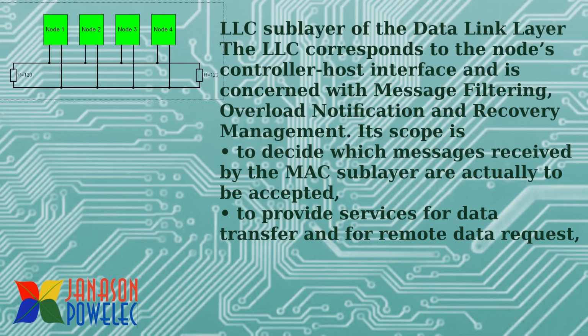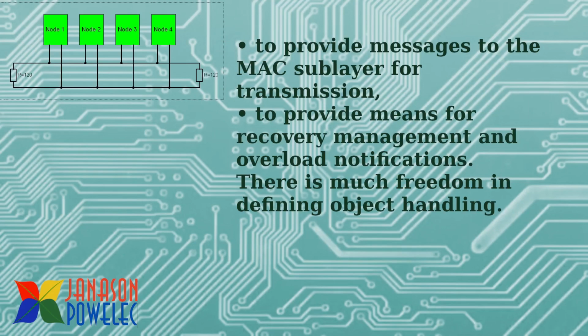Its scope is to decide which messages received by the MAC sublayer are actually to be accepted, to provide services for data transfer and for remote data request, to provide messages to the MAC sublayer for transmission, and to provide means for recovery management and overload notifications. There is much freedom in defining object handling.